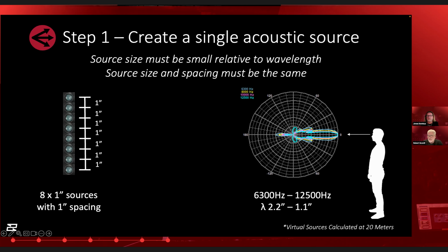This is a fundamentally important piece of information to have. We are able to create this because there is so much overlap in these drivers, right? Remember, they started as omni. Now we've stacked them together and created this very narrow pattern. It is honestly really analogous to what we do with subwoofers, right? Why can we steer subwoofer energy so dramatically? Because there's so much overlap in it, right? So the overlap is a key tenet of this whole process.